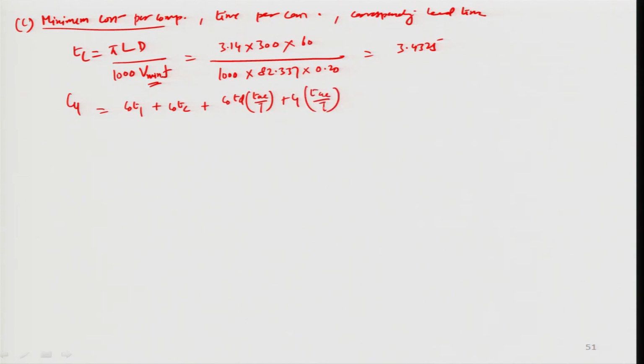T. So, in this particular case we calculate the C0 as 0.25, which is the machine labor and overhead rate corresponding to the situation that has been described here, times of the T1, which is actually the non productive time consisting of loading and unloading of the part in minutes.